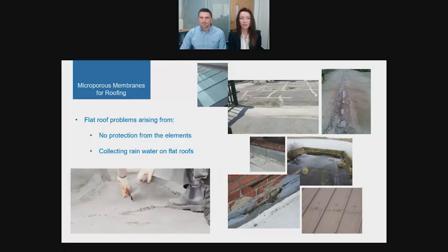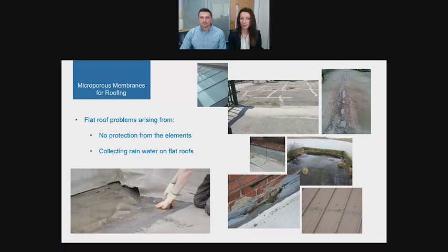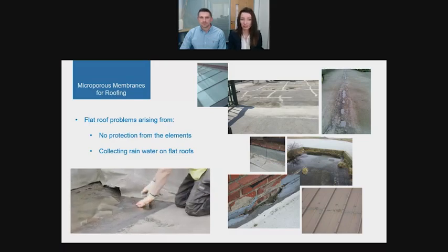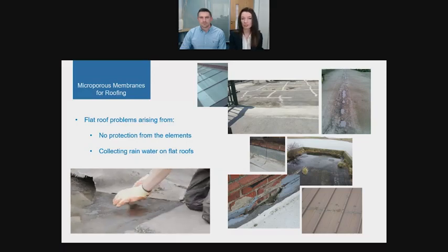On a flat roof, any rain can easily start to pool, and even if there are gutters or a slight incline to try and prevent it, this may not be enough. The weight of pooling water can lead to deflection and subsequent issues, and as you could have seen in the video at the bottom of the screen, even if it seems like the original membrane is protecting a roof, if it is disbonded from the substrate and subjected to localized damage, water can collect underneath.